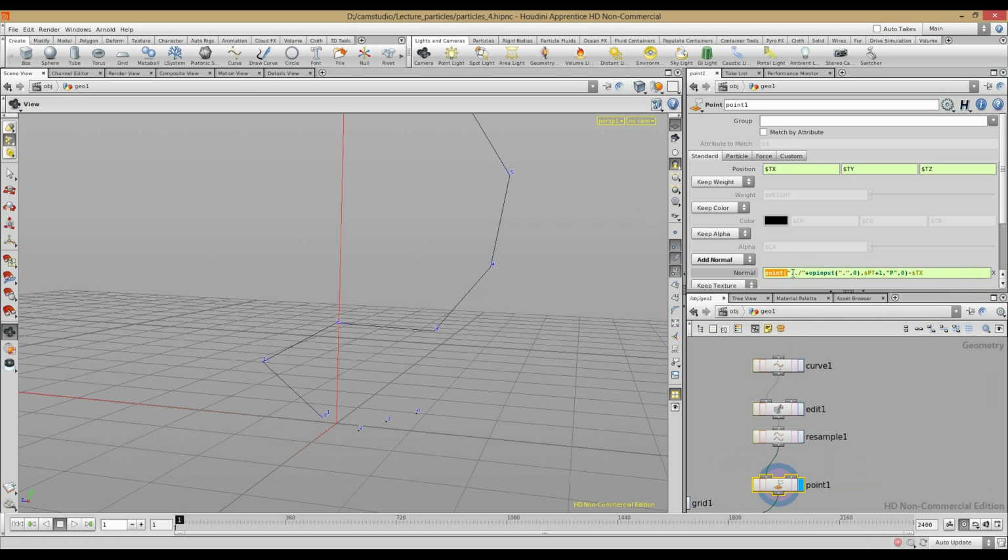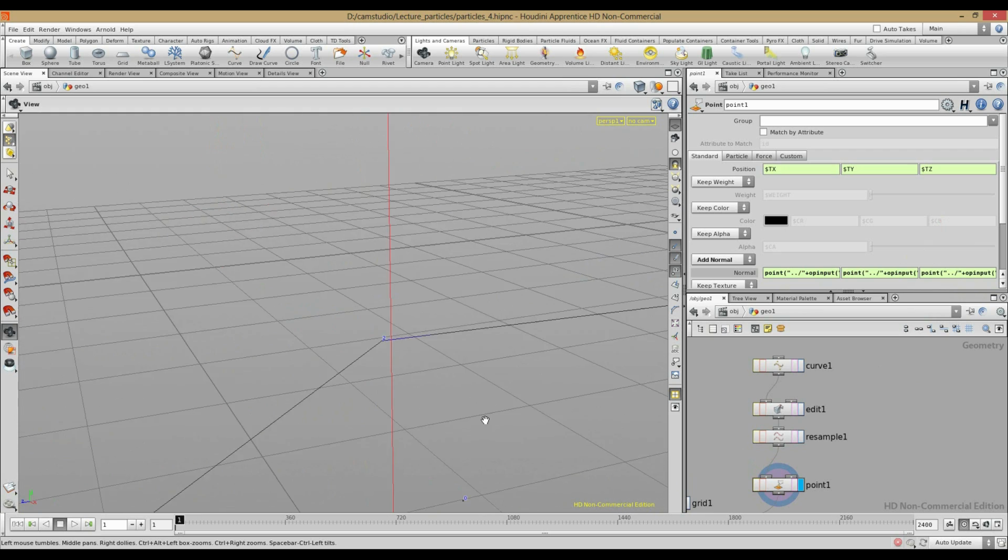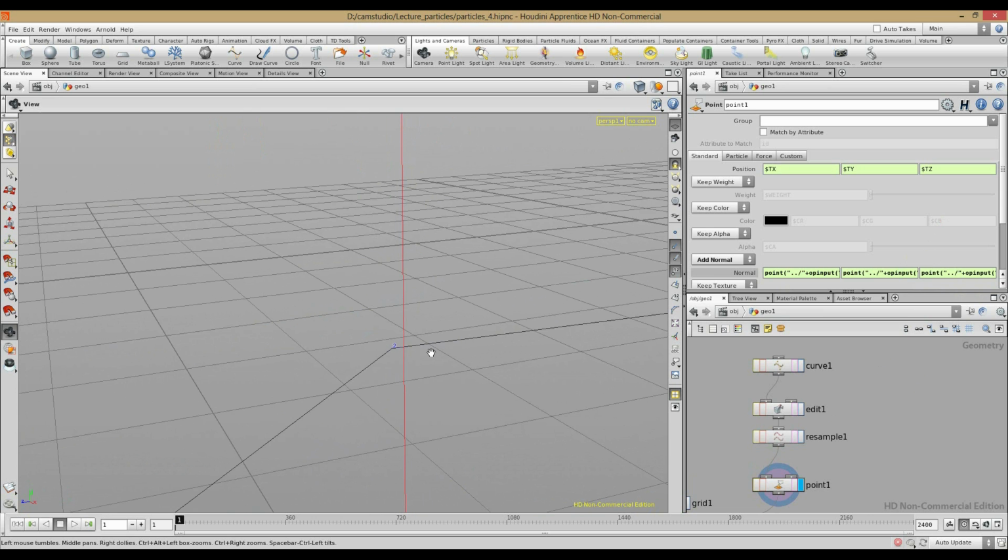Next point is taking the parameter from a specified point. And here I'm telling the expression from which node I want to take this point. Then I'm saying which point number it is, then attribute, and if something goes wrong, this will be 0. Alright. So now I have my normals pointed in the right direction. You see it goes here.